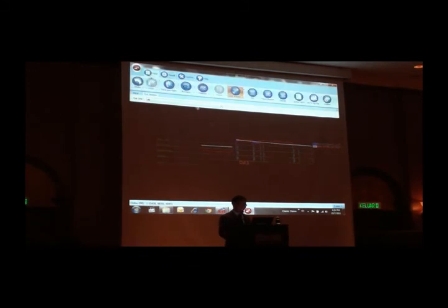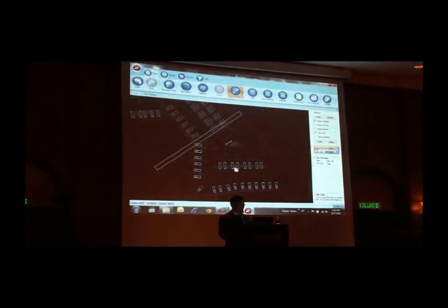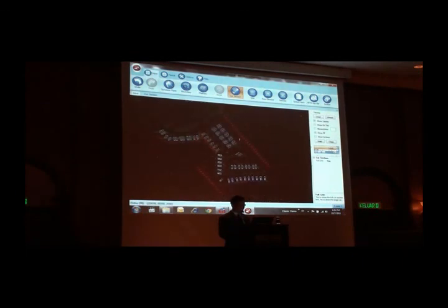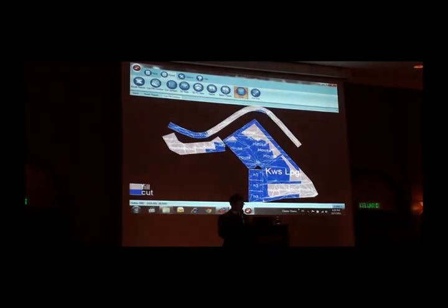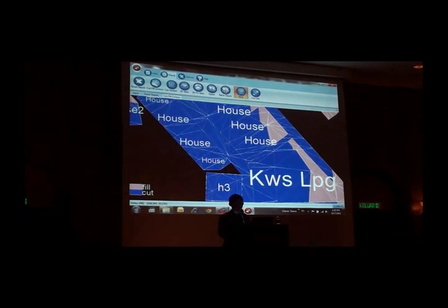Okay. So come back to the input. So I think that's all for the input part. We can analyze. Okay, I will skip the grid system. Actually, our software we have DTM and the grid. So if I skip the grid, we tell the program only DTM. Then we click OK. So finished. So we can see the meshing. This is the thin method DTM meshing.